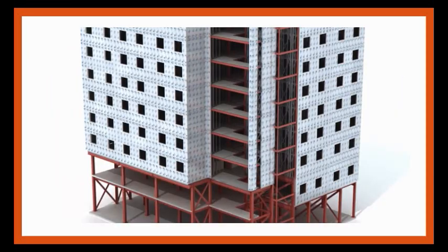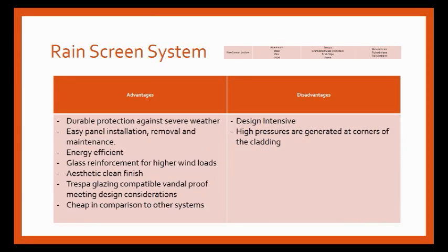A rain screen cladding system usually consists of insulated panels with a non-permeable glazing for good water resistance. The panel is also positioned with a ventilation profile in between the insulation and panel, so any rain that does penetrate the panel doesn't reach the internal part of the building. Rain screen can also be cheap with the right materials, making it a versatile system.